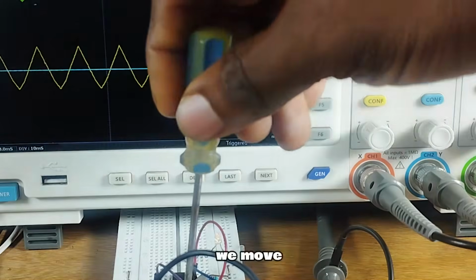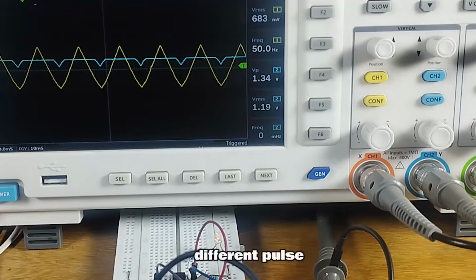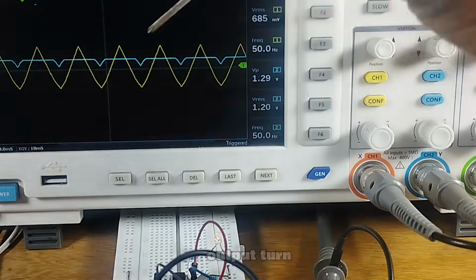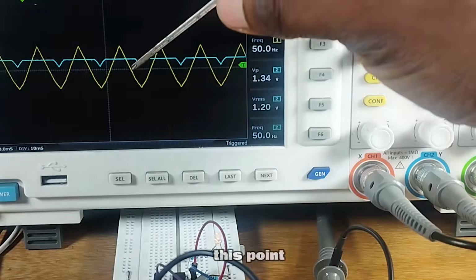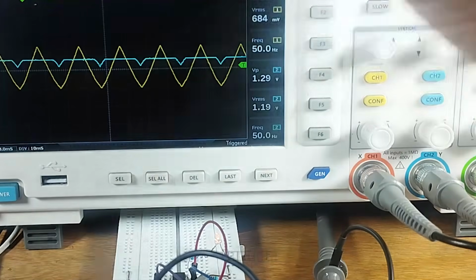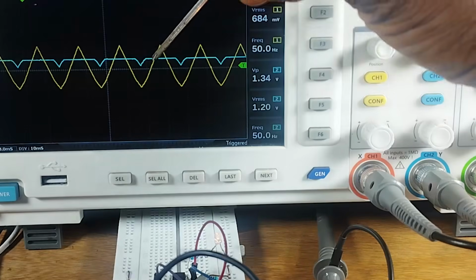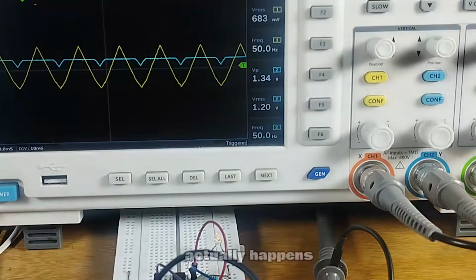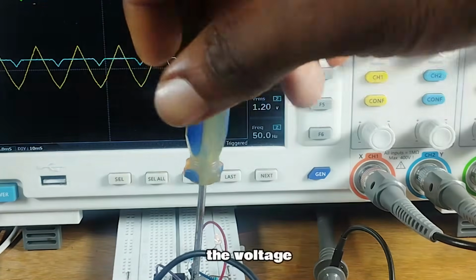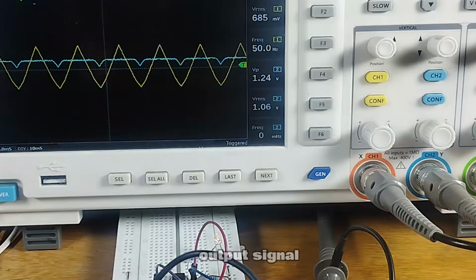Now if we change the DC level to 1.29 volts, that will mean we have a different pulse width, because previously we had our output turn on at this point and turn off at this point, but right now we're going to have our output turn on at this point and turn off at this point. So you see we have a wider width. That's what actually happens. The voltage level changes, and as it changes, the threshold for our output signal changes.